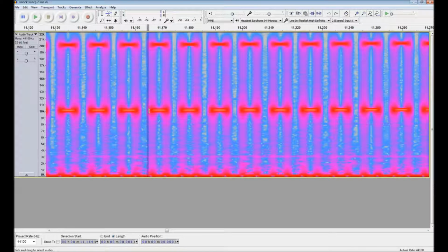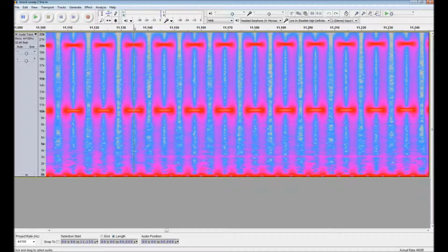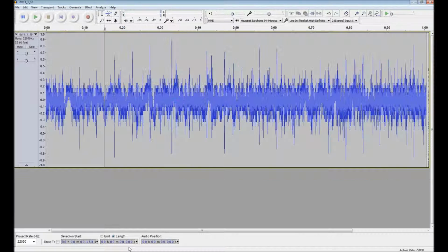The pulse width from the start to the end is 10 milliseconds on the dot, every time, every ignition event. So this is the pause when the engine is not igniting anything, like ECU, and this is like cylinder 1, 4, 1, 4, 1, 4, and so on. And you can see the intensity is pretty high, even though the duty cycle is low. But I will show you how a real knock sounds and looks like.